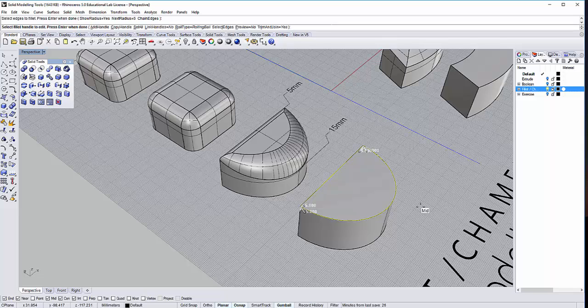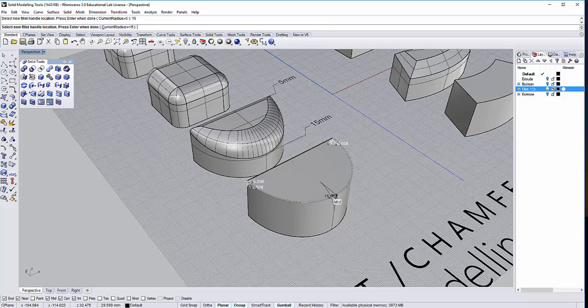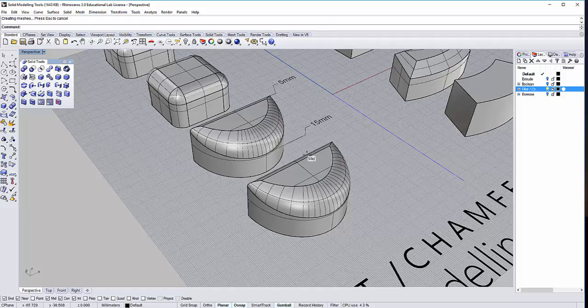Once you press enter, they will ask you whether you want to edit the handles or not. It's the same thing as just now. Right now it's registering 5, 5, 5, 5, but I need another 15 here. What do I do? Go to the top here, add handle, the same thing, input 15, because I know I want a 15. Find my end intersection, drop it, press enter. Because why? I want to escape from my new handle location. So right now they're asking whether you want to edit any of the handles. Not really, right? So just press enter when done, and then you get it.